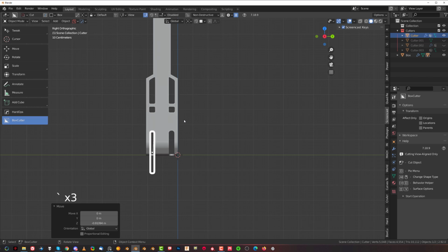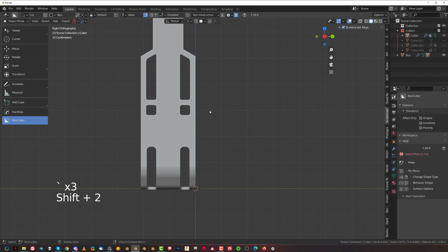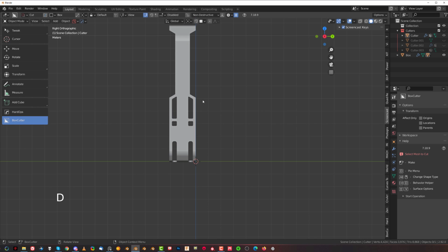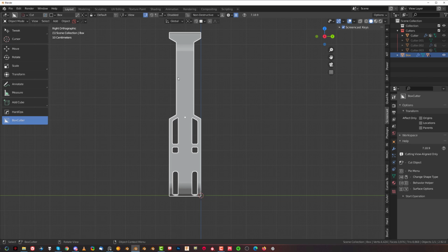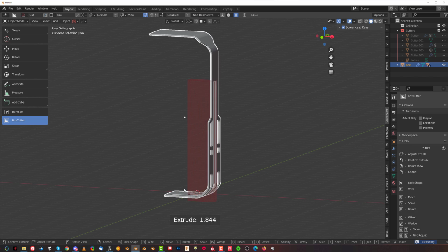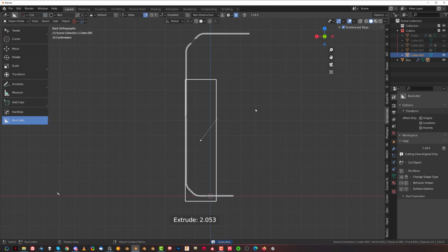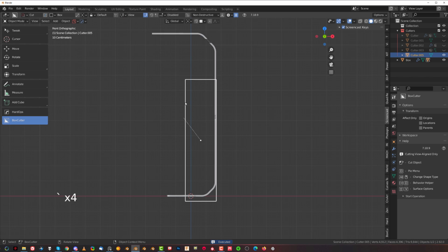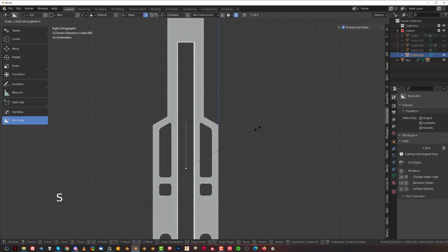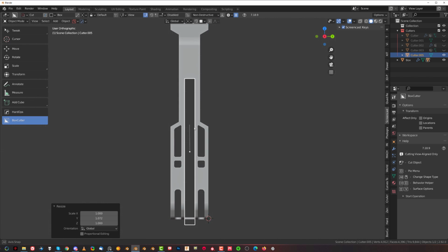All right. So let's go to the back view and let's make it even lighter. Okay, so let's grab a square, the box, select this shape, and let's cut it in here in the middle. Maybe somewhere here like this, right? And cut it through. Shift click to live. And now we can manipulate with this cutter a bit. So let's expand it on the Y axis, so S Y. Make it a bit wider.